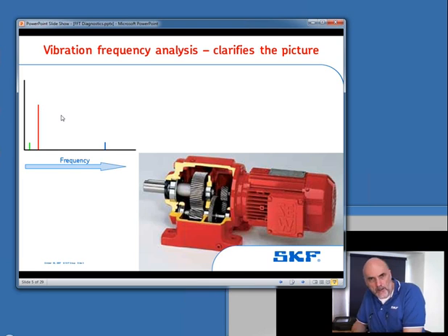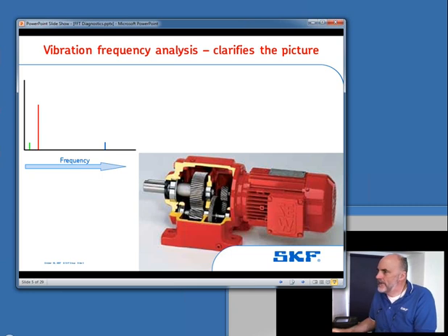What you're doing in diagnostics when you're using an FFT analyzer is you're looking at the shape of that spectrum and you're looking for those troublesome frequencies. And there's no real black art to this. A long way to successful diagnostics is knowing what's inside the machine. So in the case of this gearbox, for example, it's nice if you have a cutaway gearbox and you can count the teeth. Life isn't like that.